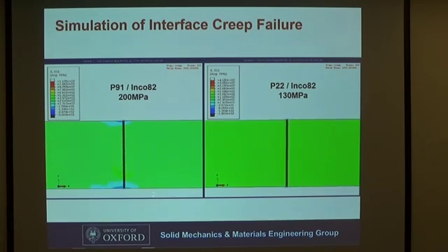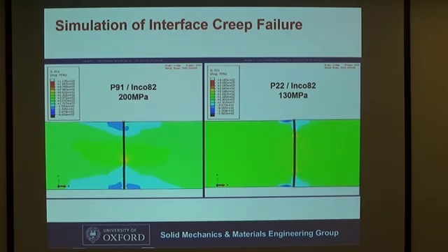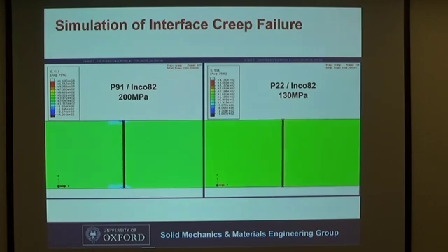But you may ask why the crack starts to propagate, but it doesn't penetrate the whole interface. That's because it's getting harder and harder for the convergence. You need to reduce even more the time step to make it converge and to move forward. But from an engineering perspective, there's no use because even if you reduce the time step, you can get a very nice visual effect of the result, and you can see the separation of the 2 blocks. But that doesn't change the part of the result.